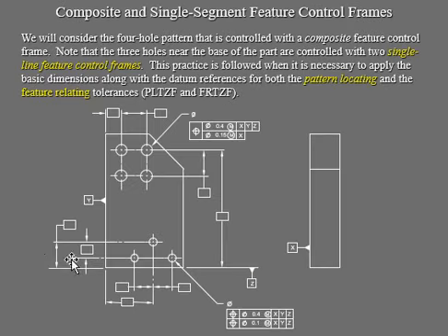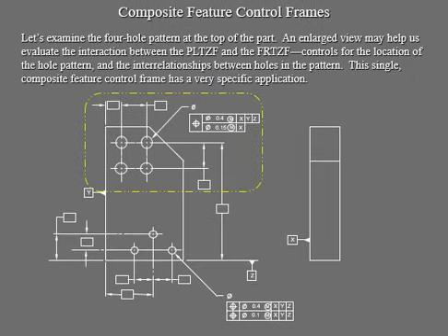So let's take a look at it in a diagram for this part. We have all of this, and you can see that the composite tolerance is giving you the information for these tiny little holes right there. This is smaller than that. And we have our y right here, and our z right here, and then your x is going to be on this view, on this side. So try to practice your different views, and then locate your datum, dealing with the pattern location of the hole, and the location of the size of that hole.